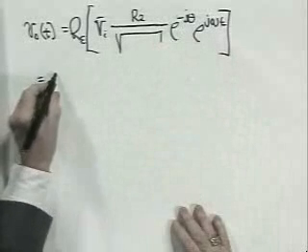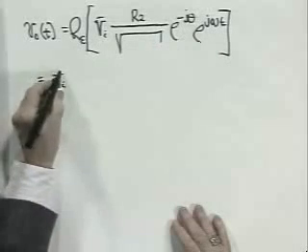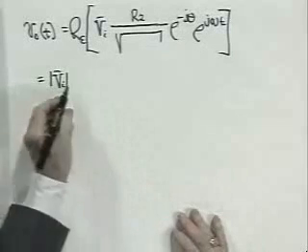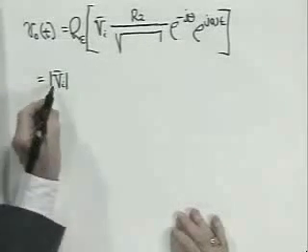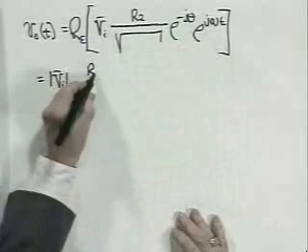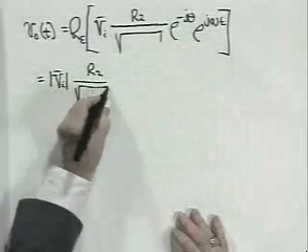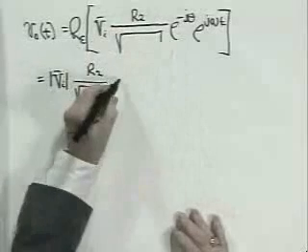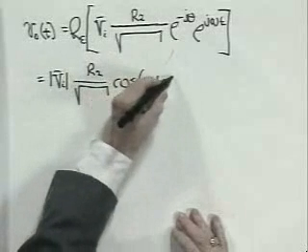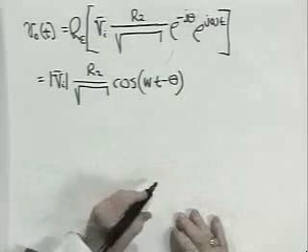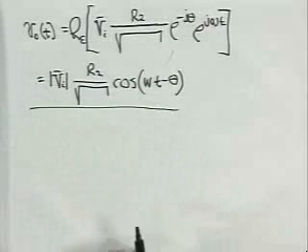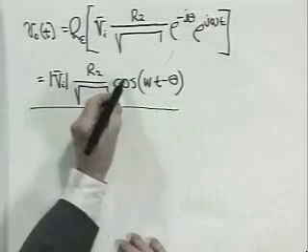So the real part of this is the magnitude of this, v sub I. Had it been a complex number, I would be looking just at its magnitude. I said at the beginning it was a real number, so that's an unnecessary step, if you will. But were it a complex number, I want just its magnitude, and I would incorporate its angle in over here, times R2 over the radical, that's the magnitude of the transfer ratio, times cosine omega t minus theta. Back to the real world. The voltage across the parallel combination of resistor and capacitor is that time function.